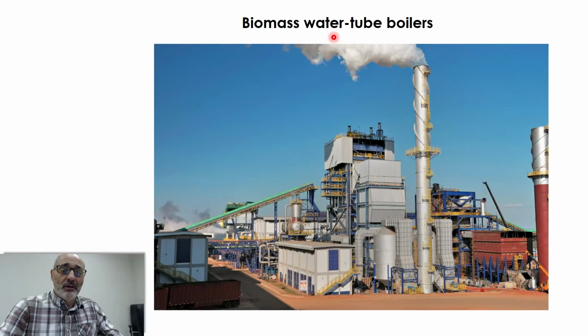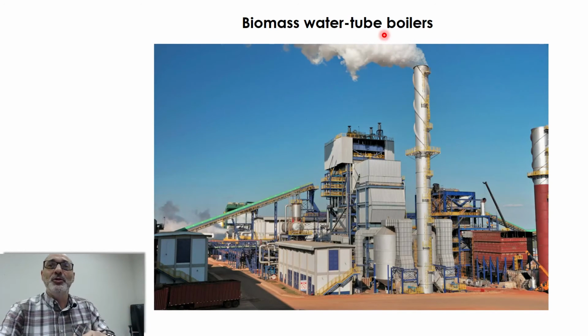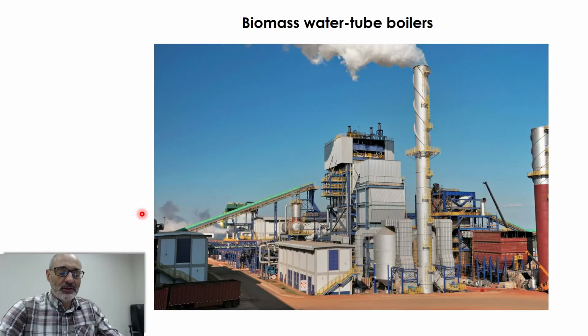Well, biomass boilers, not biomass oxy-fuel boilers, but biomass boilers, are actually water tube boilers. That means that water runs inside the tubes and the combustion gas from outside. This is a very mature technology, especially for sugarcane bagasse here in Brazil. This is a typical biomass boiler for sugarcane bagasse.